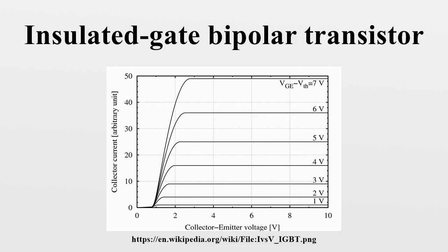V constant voltage source and were switched on for 25 microseconds. The entire 600 V was dropped across the device and a large short-circuit current flowed. The devices successfully withstood this severe condition. This was the first demonstration of so-called short-circuit withstanding capability in IGBTs. Non-latch-up IGBT operation was ensured, for the first time, for the entire device operation range.